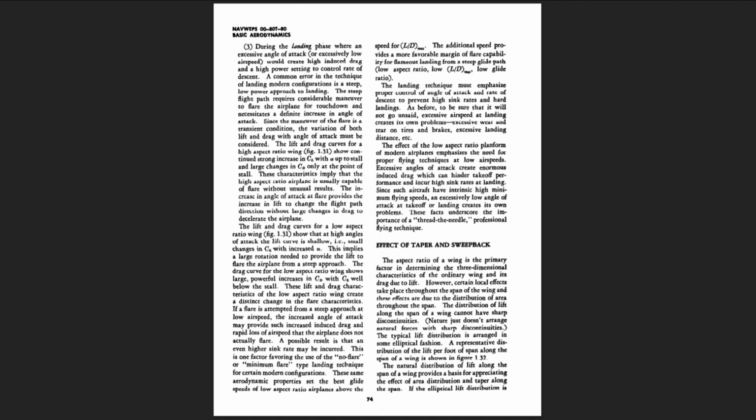3. During the landing phase, where an excessive angle of attack, or excessively low airspeed, would create high induced drag and a high power setting to control rate of descent. A common error in the technique of landing modern configurations is a steep, low power approach to landing. The steep flight path requires considerable maneuver to flare the airplane for touchdown and necessitates a definite increase in angle